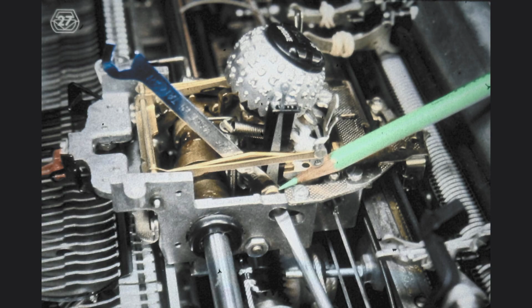Beyond the maximum power drive position, the remainder of the distance between the platen and the type element must be traveled by the element under free flight conditions, in which the momentum acquired during the powered flight, or simply the inertia of the moving rocker, must continue to overcome the tension of the restoring spring as well as eventually produce the impression on the paper.